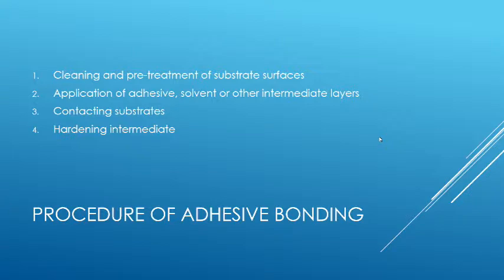First, cleaning. Second, apply the adhesive. Third, contact the 2 or more substrates. Fourth, hardening the intermediate.